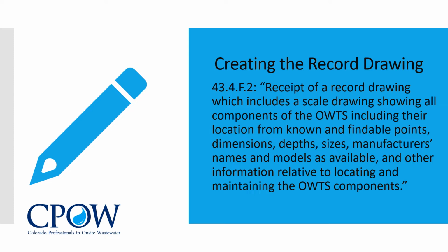So what does Regulation 43 say? Receipt of a record drawing, which includes a scale drawing showing all components of the OWTS, including their location from known and findable points, dimensions, depths, sizes, manufacturers' names, and model numbers as available, and other information relative to locating and maintaining the OWTS components.